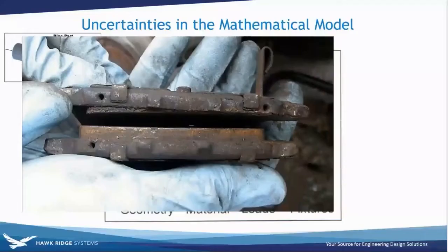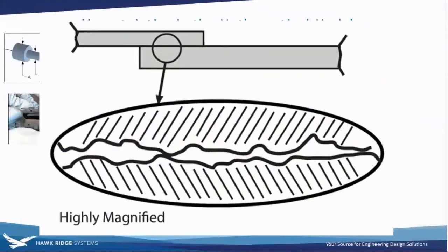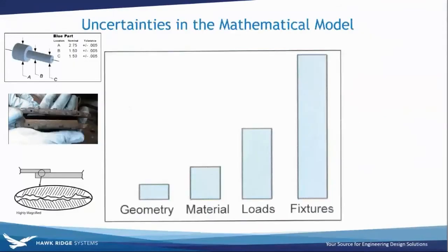So what SolidWorks thinks is perfectly flat and planar, you zoom in real life and it looks like not flat and planar. And then there's other imperfections as well. So these anomalies are usually insignificant, but they can account for some error when comparing your simulations to real-world empirical testing. The material model you use is the next source of potential error.